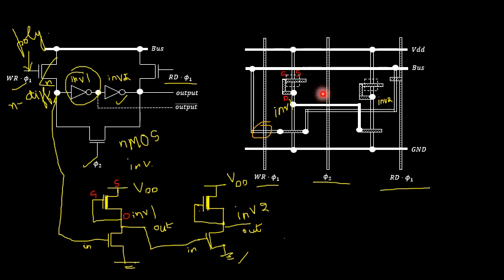What happens is, the inverter 2 output in turn should get connected with the phi 2 signal, the diffusion part. So this is the phi 2 signal transistor. The inverter 2 output has a connection with that particular phi 2 transistor, the other side of the diffusion terminal, and then it has to get connected with the input. This I have already explained.